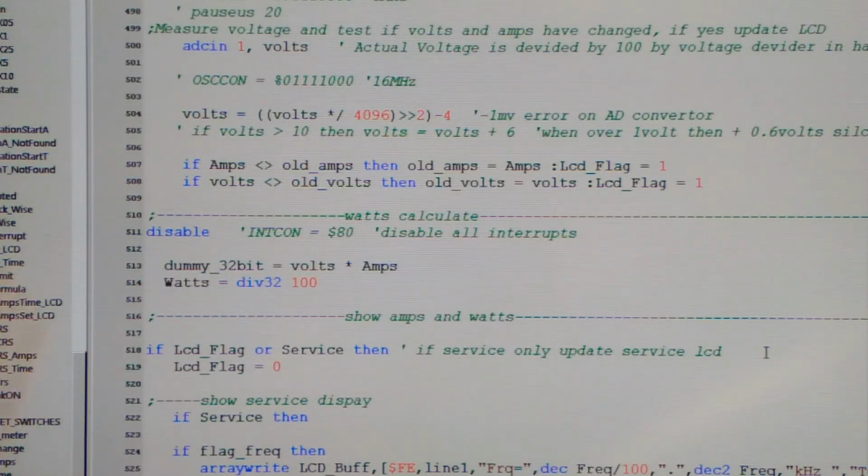If the value has not changed, so it's still 4 volts, you've read it again, and you're reading it here in this command, right? In Arduino it will be in a different section how you read it. You store the last value that you read in a variable. Now you read it again. So you're going to test whether that last value has changed.